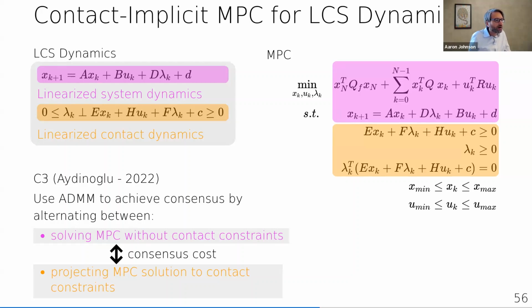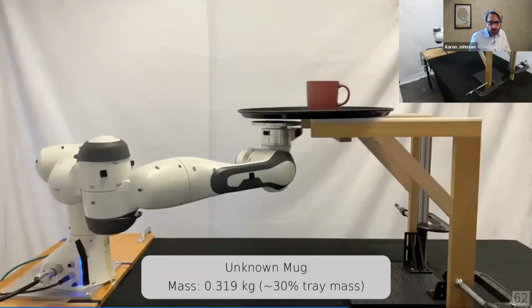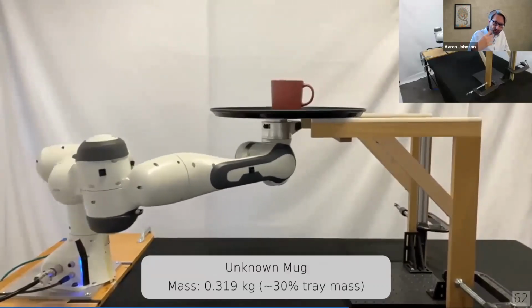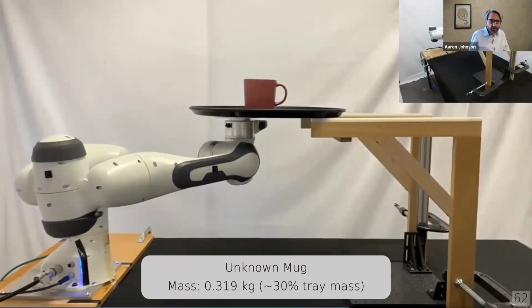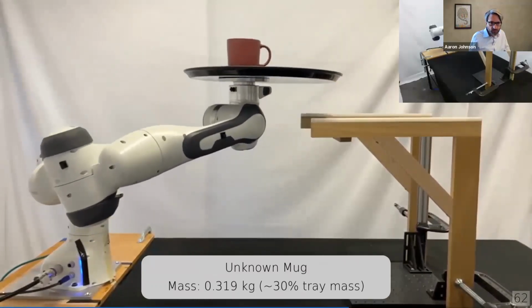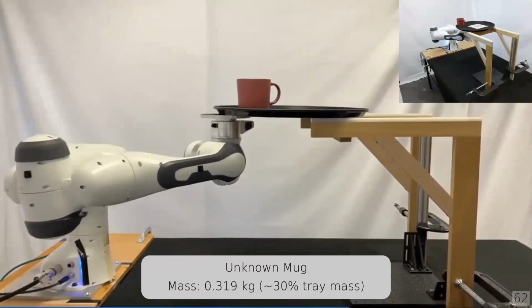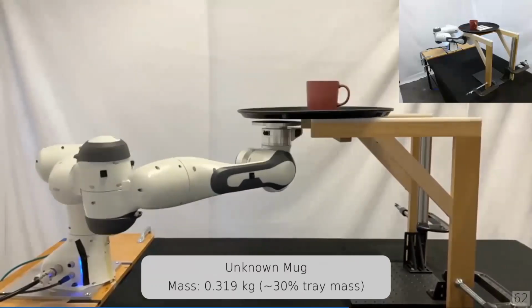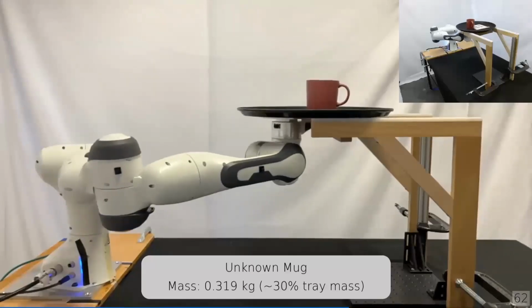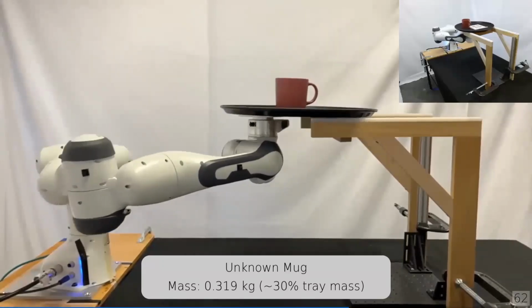Okay. All right, and then looking at the results there, I was looking especially at the one with the mug. So it kind of does this pawing motion where it tries a couple times and goes back. Is that an emergent property? This sort of try again? Yeah. There's no predefined number of times it's trying to pull it. It just keeps trying. I mean, this all comes out of contact-implicit MPC. I'm not pre-specifying anything about this.